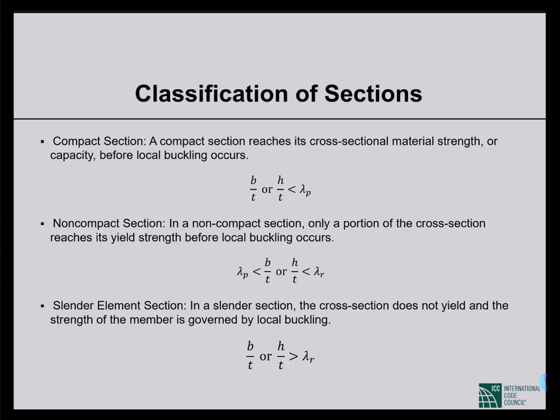Slender sections will experience elastic buckling. That is, they will experience local buckling. There will be no yielding anywhere in the section. There will be local buckling. So this is all about local buckling. Remember,